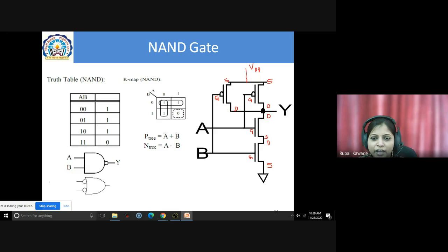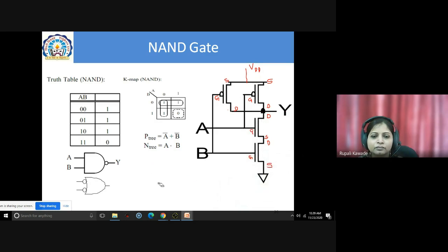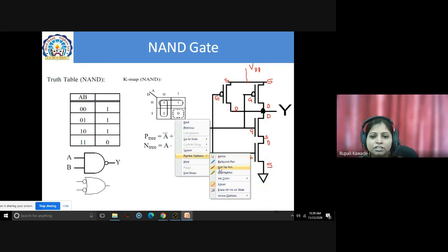That's why if this is my one transistor, then these will show you the two transistors. So the diffusion layer is common. They will be differentiated with the help of this gate and whatever interconnection we want in between these gates. So for this, how to draw the circuit? How to draw the stick diagram?